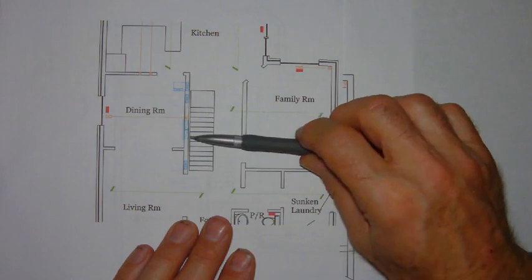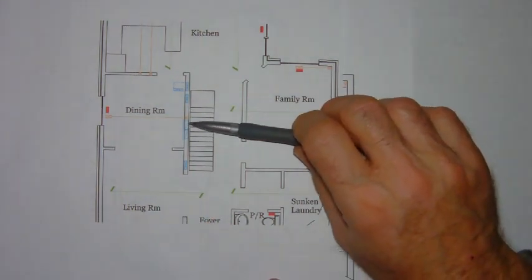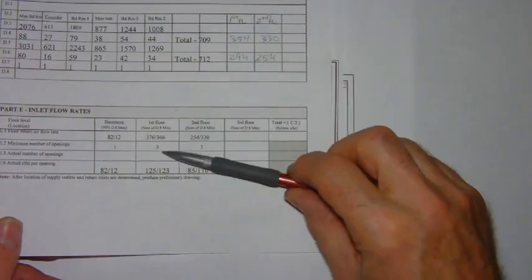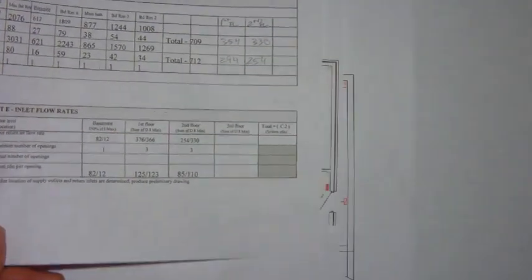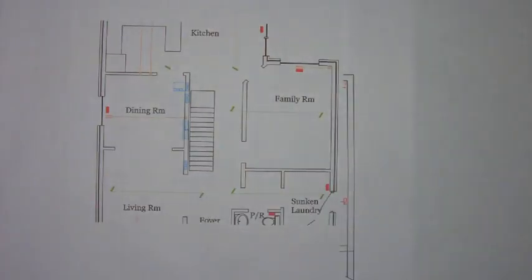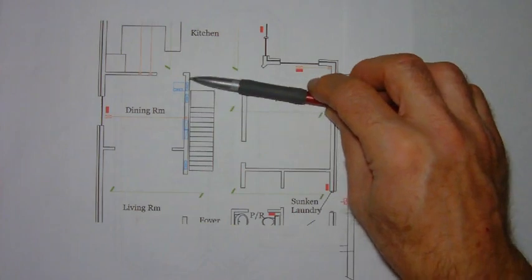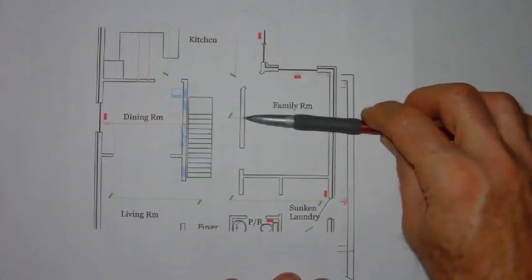The next thing we want to look at is the number of return air locations on the first floor. Now, it's recommended that we look at 3 inlets on the first floor, but keep in mind that on the first floor we often have larger walls, and in this case we've got some 2x6 walls here.